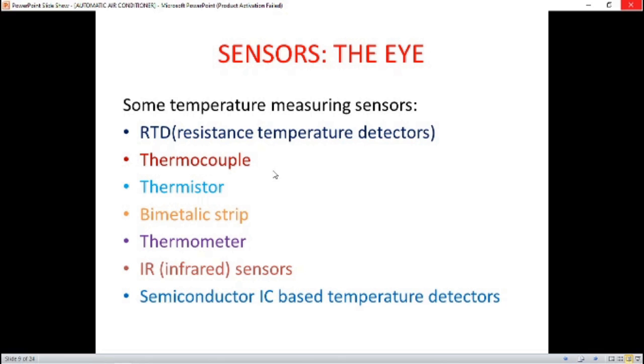For example, an IR sensor is best suited when we are trying to find out the temperature of a certain object. Say a cricket match is going on and the hotspot technology is used, so that we just want to know whether the ball has touched the bat or not. At that place the IR sensor will act very accurately. The working principle of an IR sensor is simply that if some portion is heated, that high temperature will emit infrared radiation, and there will be infrared detectors that detect that temperature, and corresponding signal conditioning circuits.